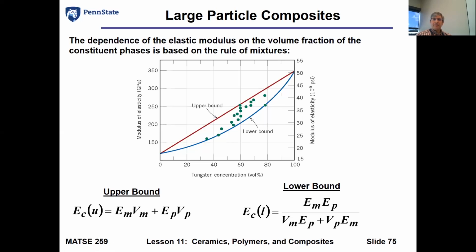Or another way to think about it is how much do we load that matrix material up with these large particle composites. And so the more you get of these particulate materials, the closer you're going to get to what the actual reinforcing material properties are going to be.